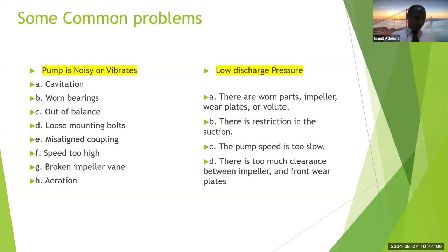So that and the low discharge pressure, these are the two things which I will say are the most common problems. And when the pump starts vibrating, one of the first things that we check is the worn bearings. So we want to make sure that the ball bearings or any type of bearings that are supporting the pump shaft are in the correct dimensional specifications, and they are not worn out, because when they wear out, the pump will become very noisy.